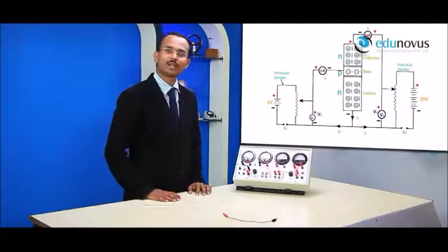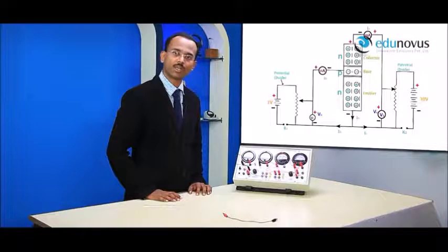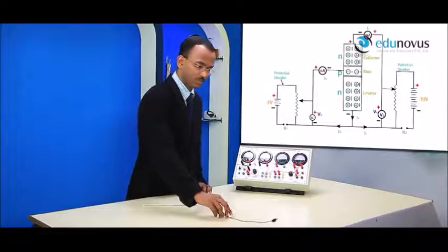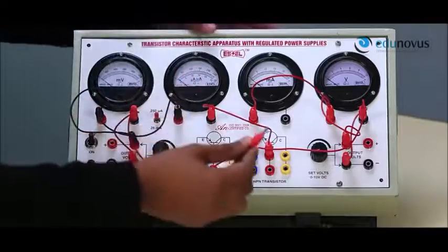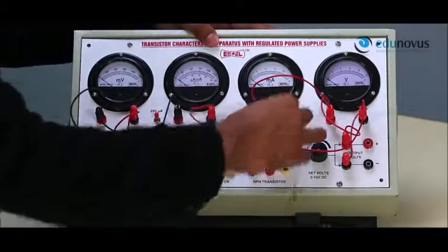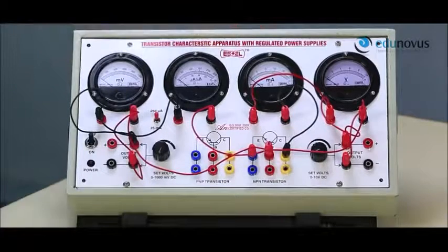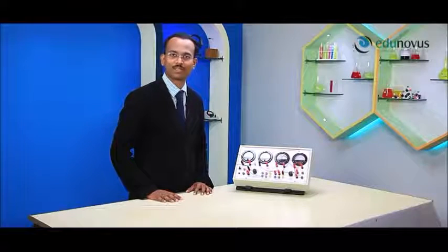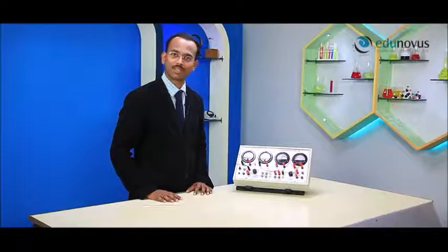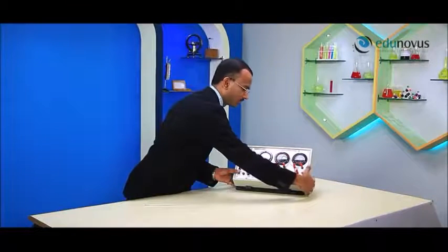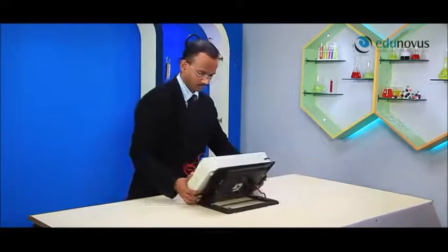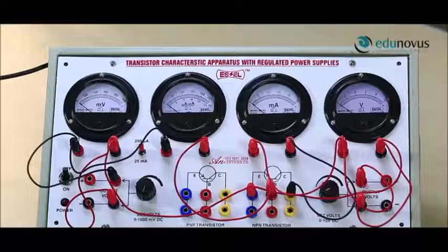And let me connect the negative terminal of the output ammeter to the collector of the transistor using this connecting wire. The connections are now complete. So let's start the experiment. Use a screwdriver to remove the zero errors, if any, in the ammeters and voltmeters.